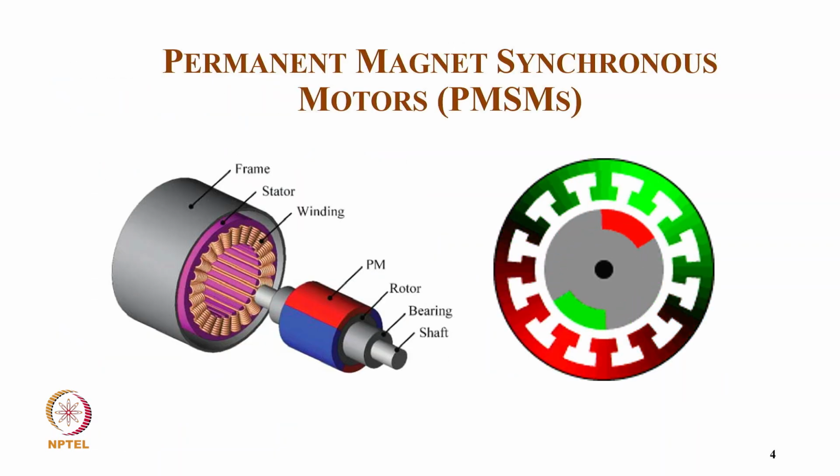So coming to the basics of permanent magnet synchronous motor drive, how the basic is there. On the stator we have normally a 3-phase winding, maybe of course other than 3-phase, 2-phase or 4-phase also, but usually 3-phase winding. And on the rotor we put the magnets in different forms, maybe buried or maybe surface mounted. So there are a lot of categories.